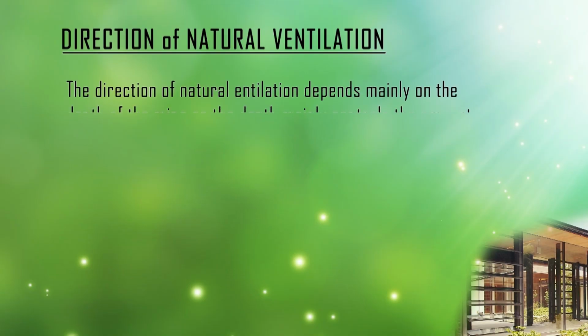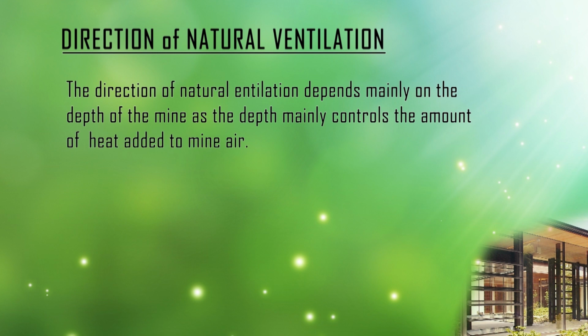Now, we come to the direction of natural ventilation. Direction means the direction from intake to return or from return to intake. The direction of natural ventilation depends mainly on the depth of the mine, as the depth mainly controls the amount of heat added to the mine air.